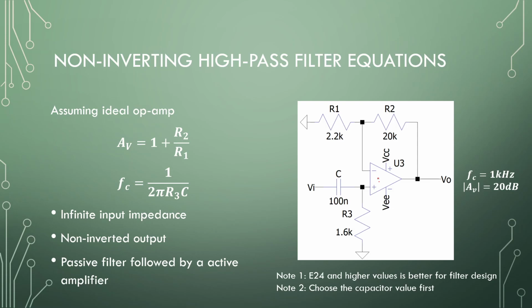So if you have issues at higher frequencies, select an op amp with a higher gain bandwidth product, and always try to keep the gain in your systems low for higher frequencies. And if you should have a high amount of gain, cascade amplifiers with a lower gain configuration that will increase the bandwidth. Okay, so let's jump over to the simulations and let me show you the response of each of these amplifiers.